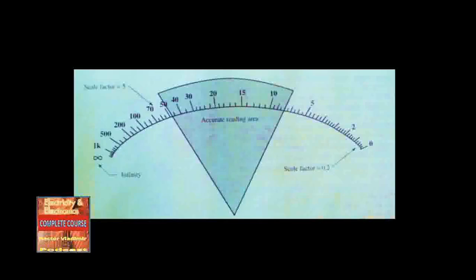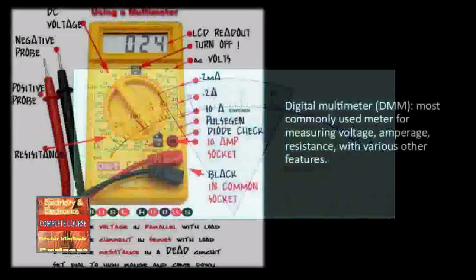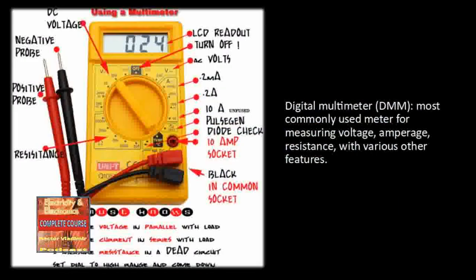Often, electronic circuits are quite compact. Be sure that the test leads do not cross over 2 or more connection points, as this could result in a short circuit. Be sure that the test leads are in good working condition. There should be no frayed or bare wiring. Make it a habit to keep your fingers from touching any exposed metal part of the test lead tips and or the circuits being tested.